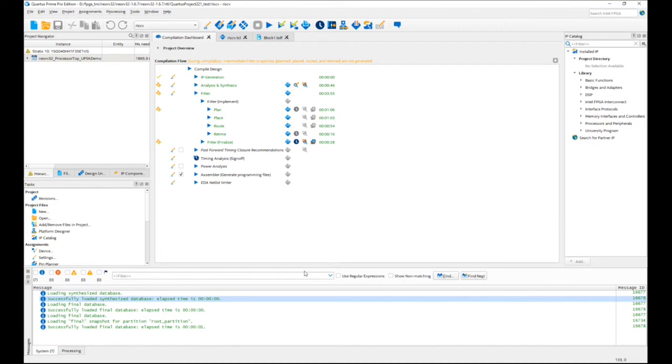If you want to do mixed language inside your design, there are no problems there. QuestaSim, which we include as the special starter edition, has mixed language support for simulation as well. Yes, that's correct. Back in the day it was always either Verilog or VHDL for simulation, but we added mixed language support a few years back as well.